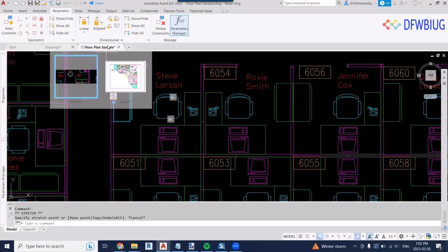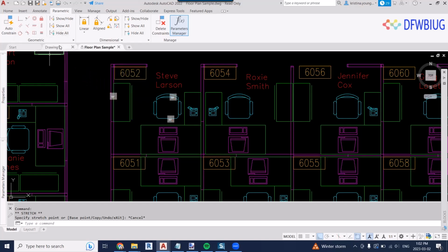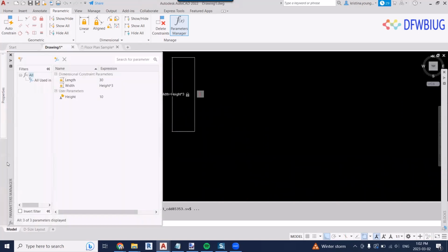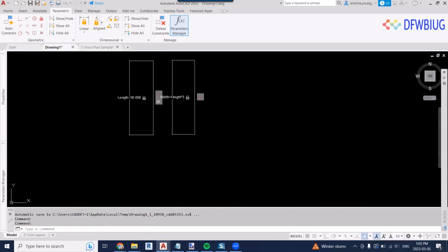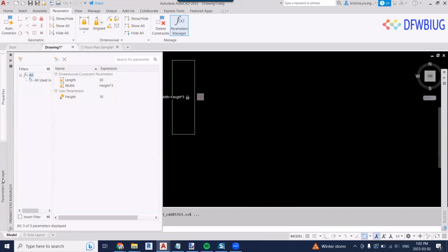They just need the CAD. They just need to know that it works. But somebody can easily go in there and say, hey, I know how to change my width. So if I set up my door family correctly and I set up my files correctly, somebody can go in there and just change their width, change their height, and still know that their model's integrity is intact. So that's what I utilize these tools for.